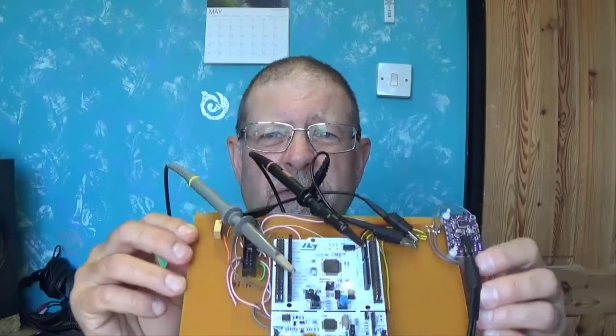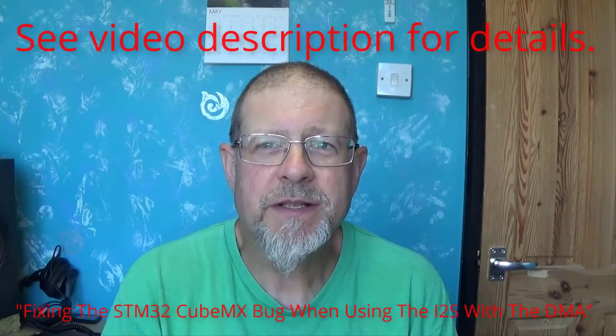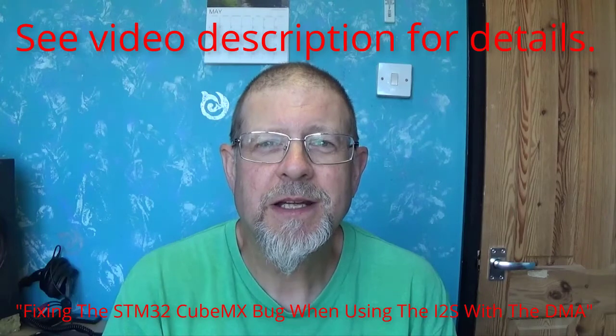And yes, we're still at the stage of a board floating about on the bench. Last time we were trying to get the audio interface working, which we did do, but we couldn't get it working with the DMA, which we really need to do. And the problem with the DMA was a bug in CubeMX and the HAL, and I did a separate video on my investigations and solution to that problem.